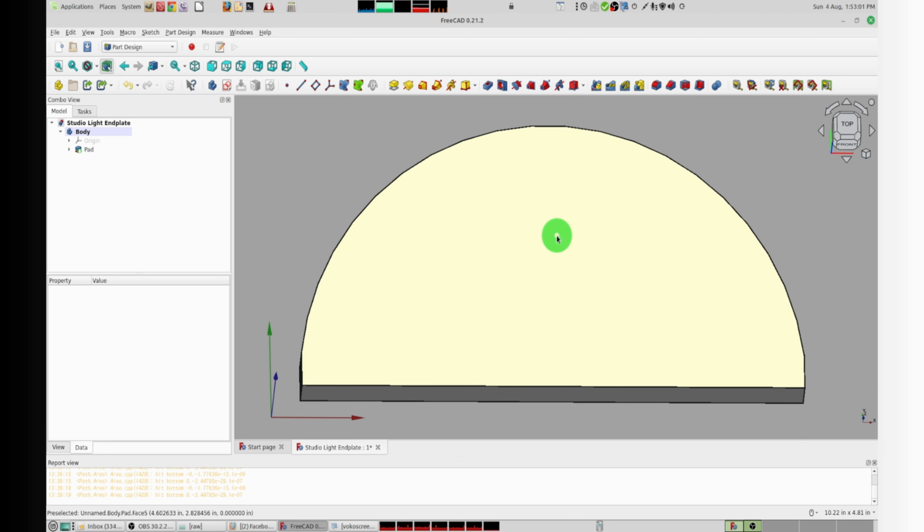Now this is the end plate. There is going to be a pair of them per light. There will be vent holes around here and 3 controls will be located here. They'll be for the colors of the lights that'll be inside, just to make them warm white or cool white. You get the idea. So I need shaft holes for the controls and recesses for the control knobs.